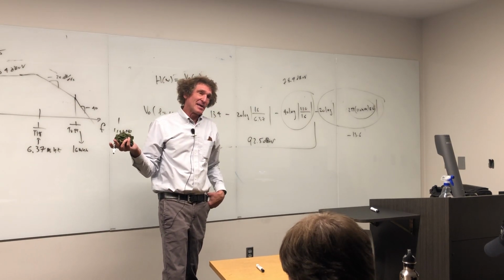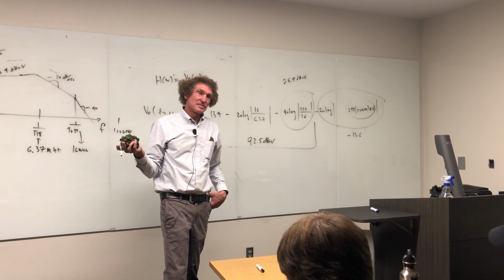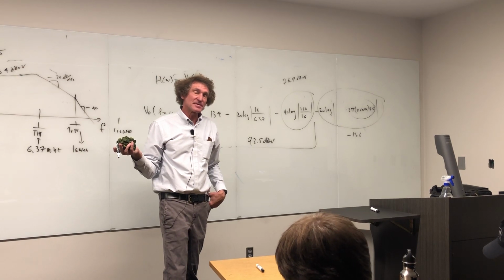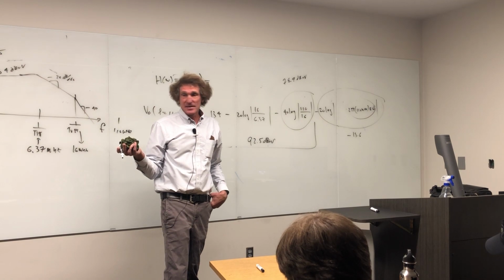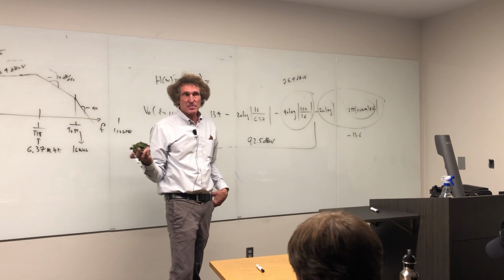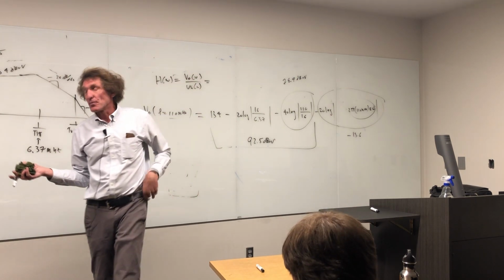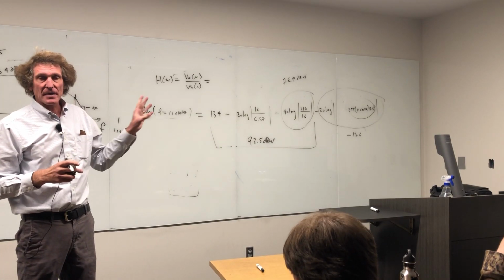78.56 decibels. We got 0.9. I'll tell you the truth: when you're talking about tenths of dB microvolts and the answers are on the order of 70, 80, you don't worry about it. And you always look for worst case. Now that tells me what the output's going to be for the worst case at that frequency.